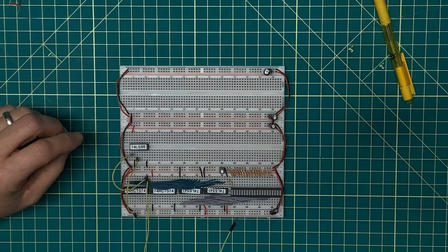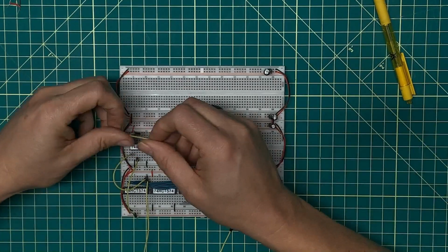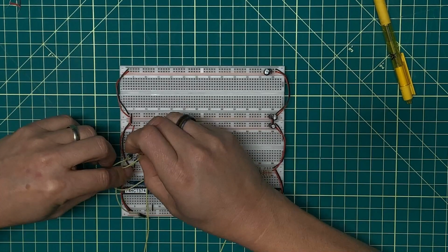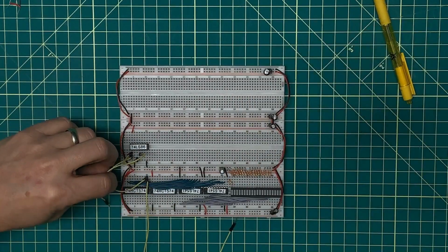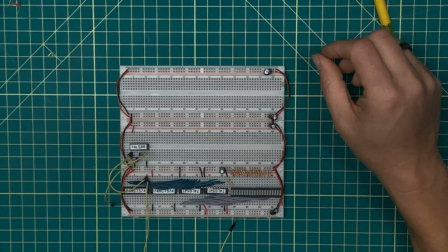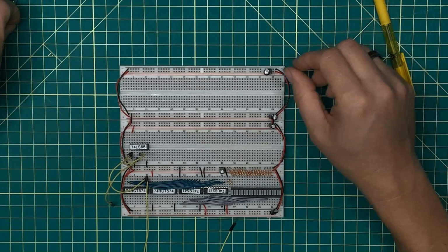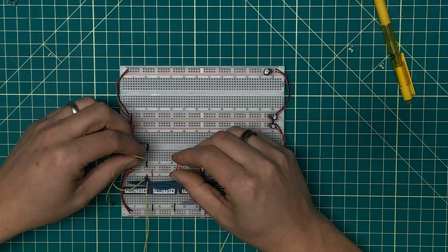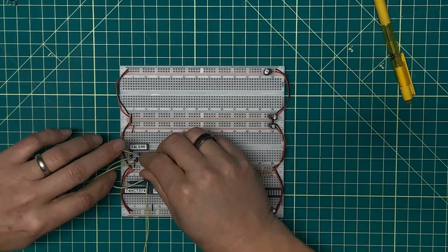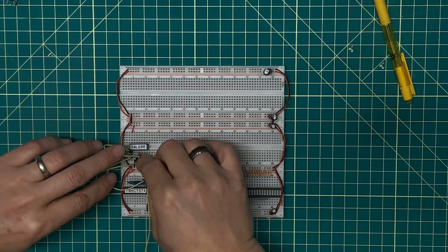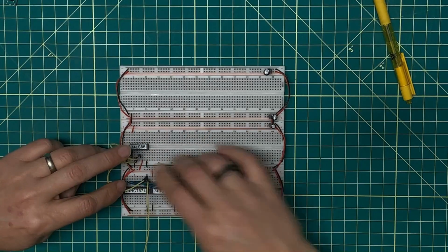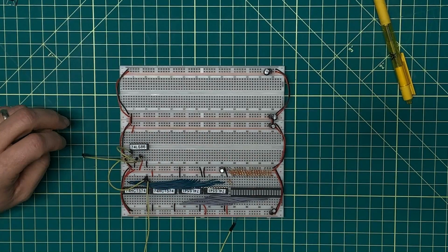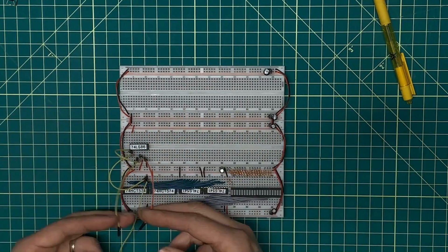Now at the same time, I'm going to take the same signal right off here and feed it into the other input of this gate. I say the other end of this gate. I'm going to tie it to the next gate over. And then I'm going to tie the other end of that high. Tie the other input high. That turns this into an inverter. And coming out of this then is an inverted clock.